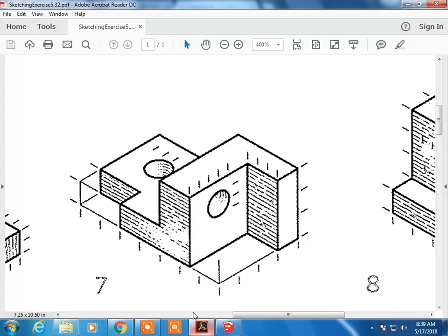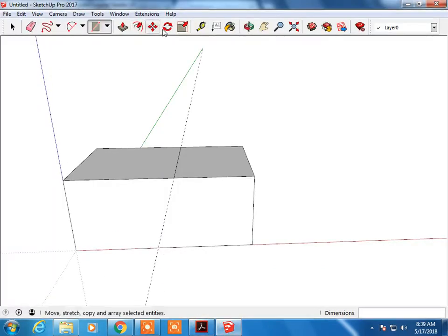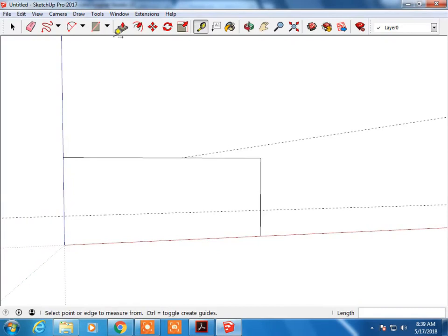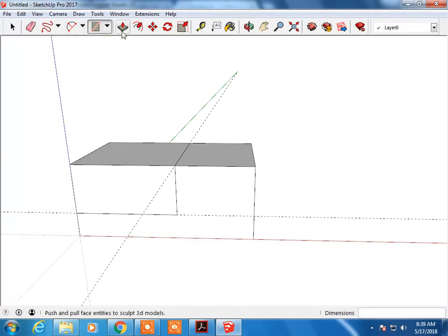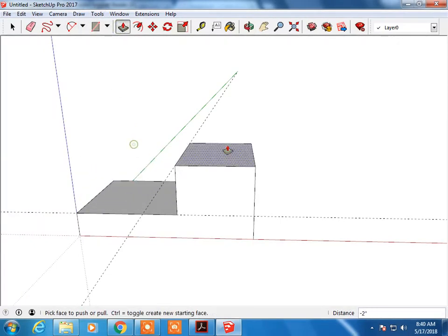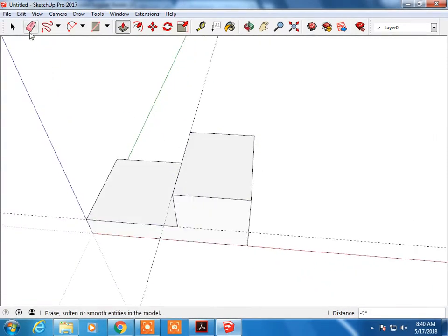And I'm going to check how thick this is. I see it's a 1/2 inch thick there. So I'm going to create a guideline going up 1/2. And then using this information here, I'm going to create a rectangle right here where these lines intersect the edge of the object. And then I'm just going to subtract this back just like that. Alright, so that's one cutout.